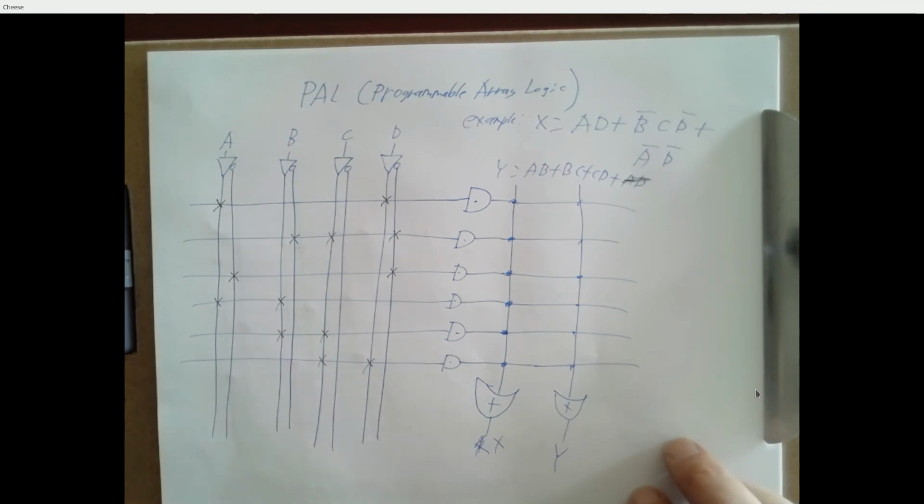Reprogrammable chips. That's harder, right? So these are one-time programmable if they're fuse-based, unless you want to have fewer connections. But in general, once you blow a fuse, you can't get that connection back. So these were the old version of these things, and they're still available. They're very inexpensive. But using various semiconductor properties, we can make reprogrammable versions of this.